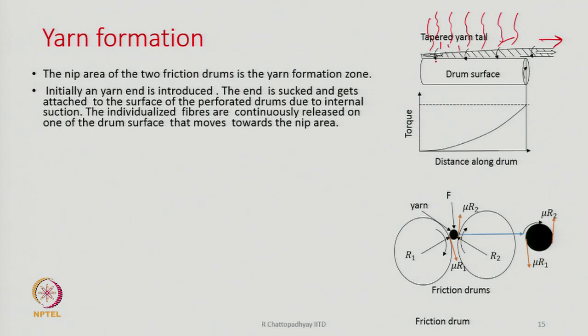Whenever fibers are coming from here, ultimately it is going from left to right. So, fibers from the left hand side, as they start moving towards the right hand side, receive more and more fibers on top of them, and therefore the yarn will be gradually thicker towards the exit end of the machine. This side is the exit.